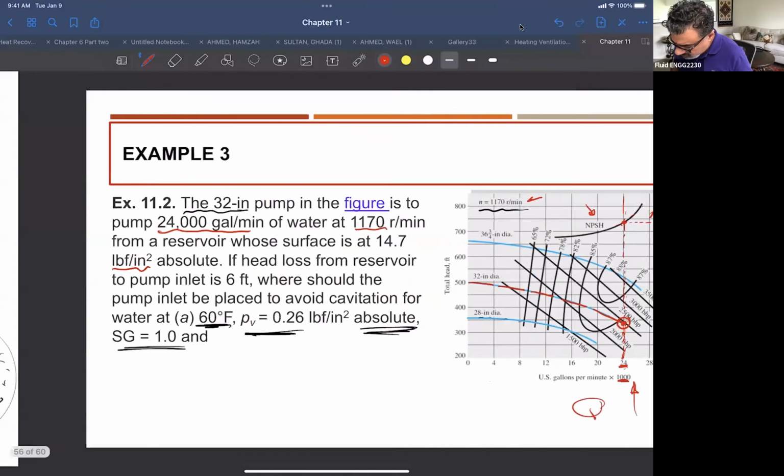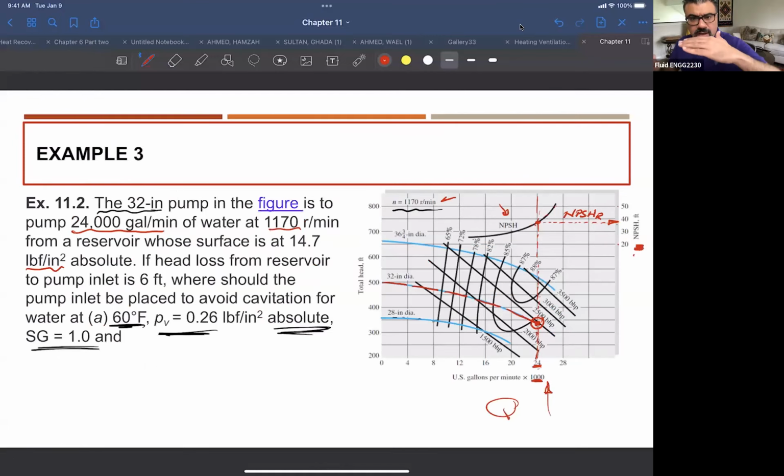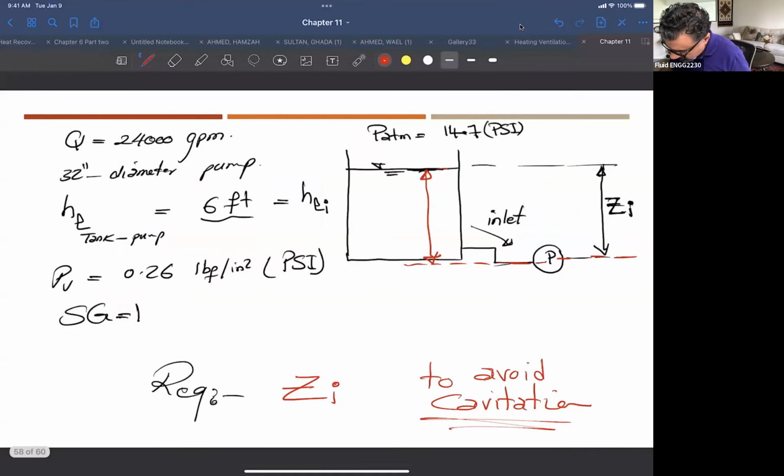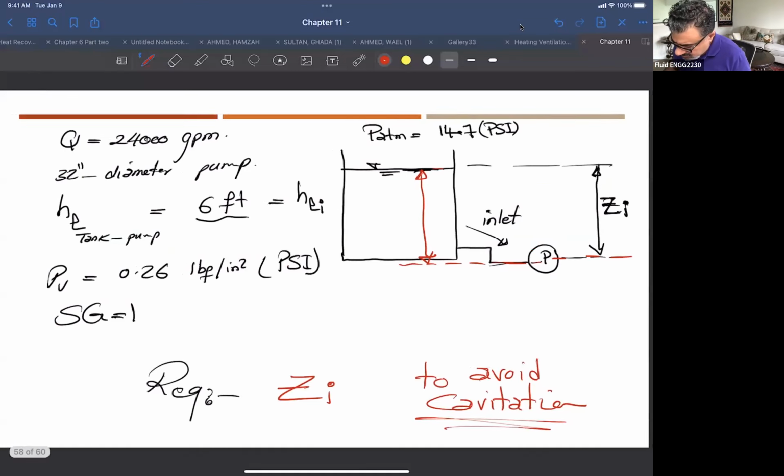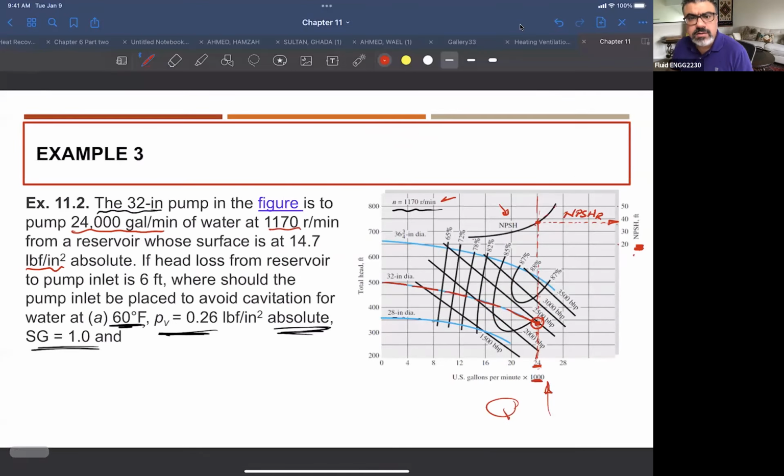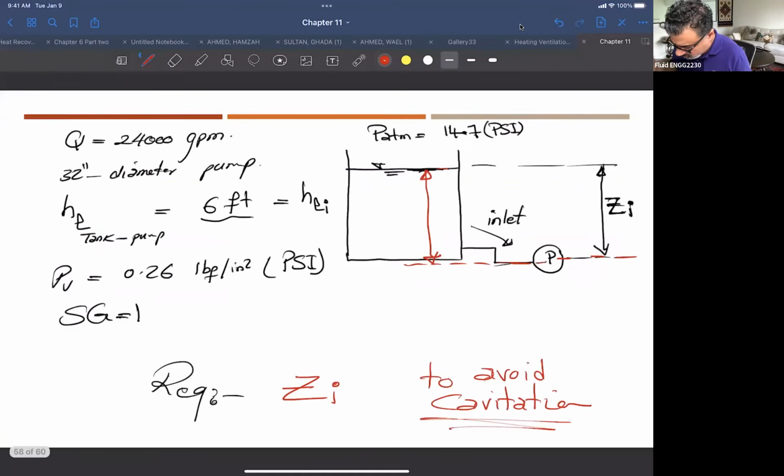Same way as these curves, right? This blue curve, the relation between the flow rate and the head, is based on the hydrodynamic design of the pump. So the relation between Q and H is all provided by the manufacturer based on modeling, design, and other things. It is very typical for a centrifugal pump to look like this, and the net positive suction head required for a centrifugal pump is always something like that. Same shape, but the value itself depends on the design.